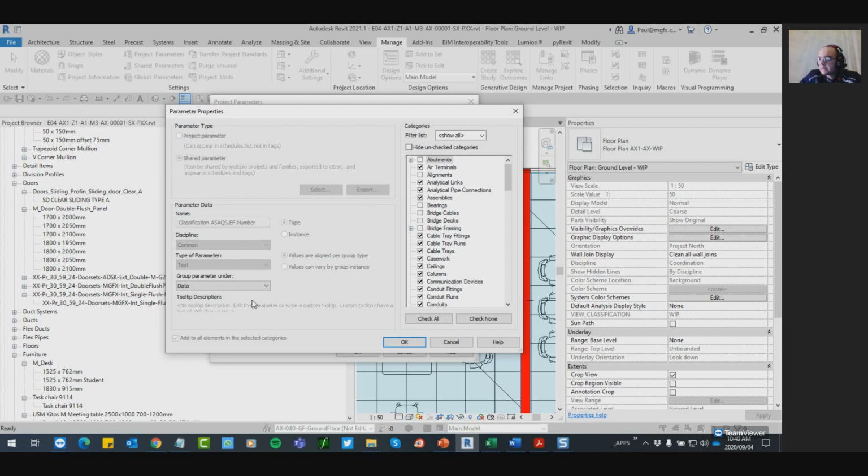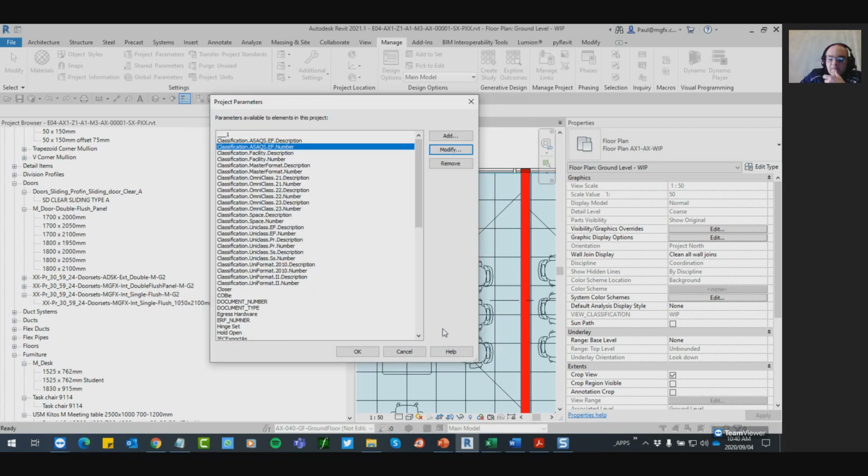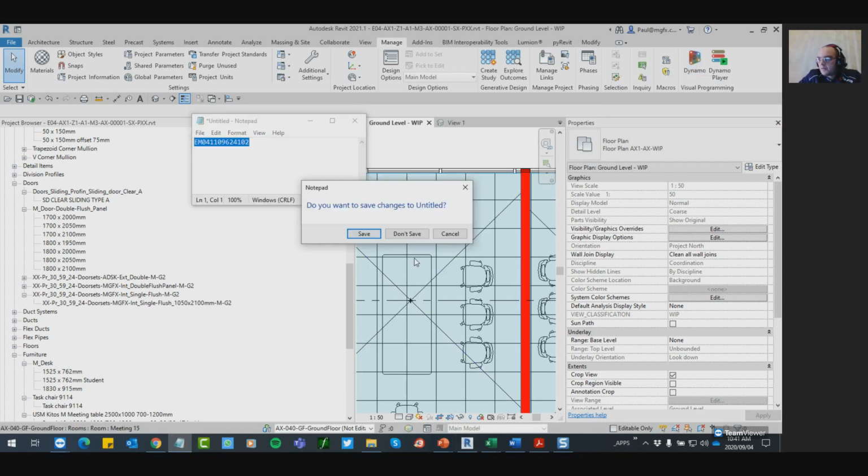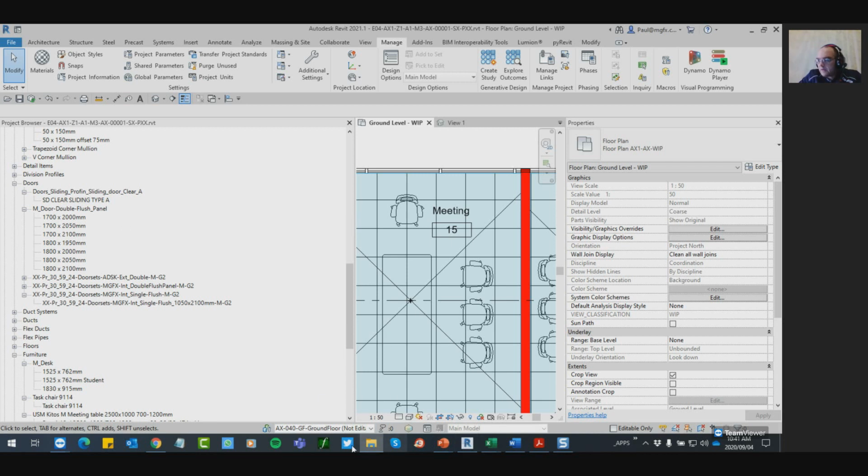So it seems they might have done in Revit 2021 something that one can't do. However, with Dynamo or in an earlier version, we can, different project possibly, we can export the GUID. So you can pick that information out of the family using Dynamo. For those of you that don't know Dynamo, it's part of Revit. It allows you to ask that information of the model. The result of that is the classification file that looks like this.